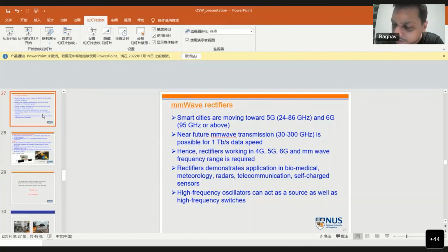Well, I'm asking this question because in a simple non-magnetic paramagnetic bilayer you can also have this spin wave rectification effect, right? Right. So how is it different from this? Because if it does not depend on the frequency, then we can have a similar spin wave rectification effect in an unpatterned film also. No, of course it depends on the frequency. In the resonant case, the frequency is near the auto-oscillation, basically the FMR frequency of the material. And the signal is very good in the spin diode, not in the other devices, because of the MR. It's directly proportional to your MR. This is a multiplication of your I into delta R, and that delta R is coming from the TMR. Okay, good. Thank you.